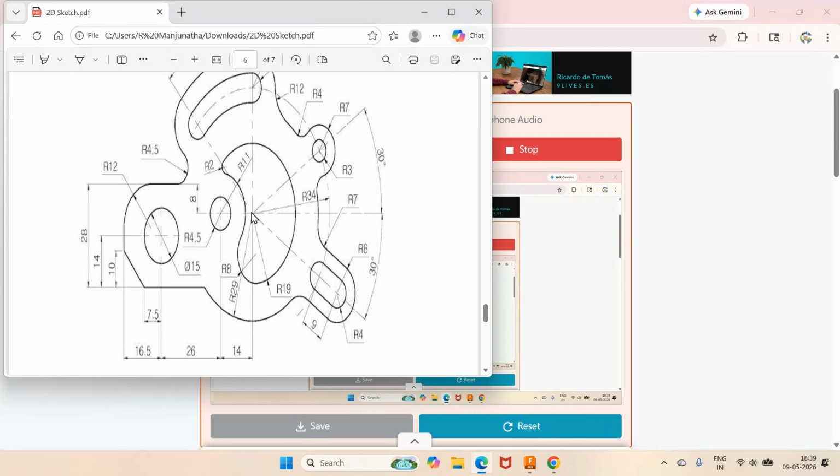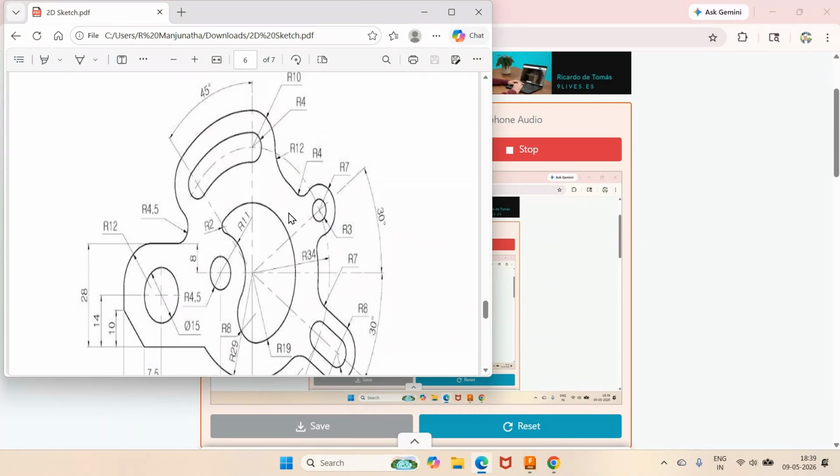In this video, we are going to take up one more problem on how to constrain this sketch both geometrically and dimensionally. To do this, first I will go to the Fusion screen, go to Sketch, create on this particular sketch, then I will go for circle and I will create a circle of radius 29.